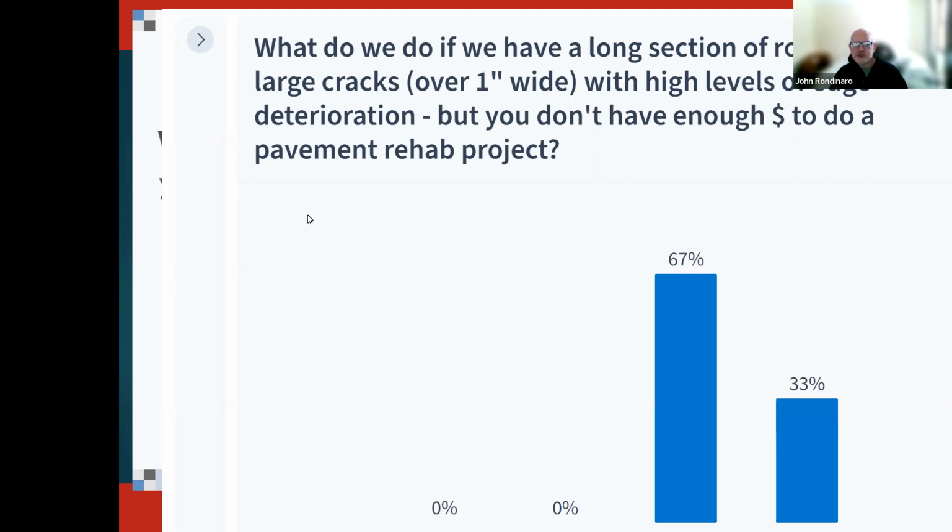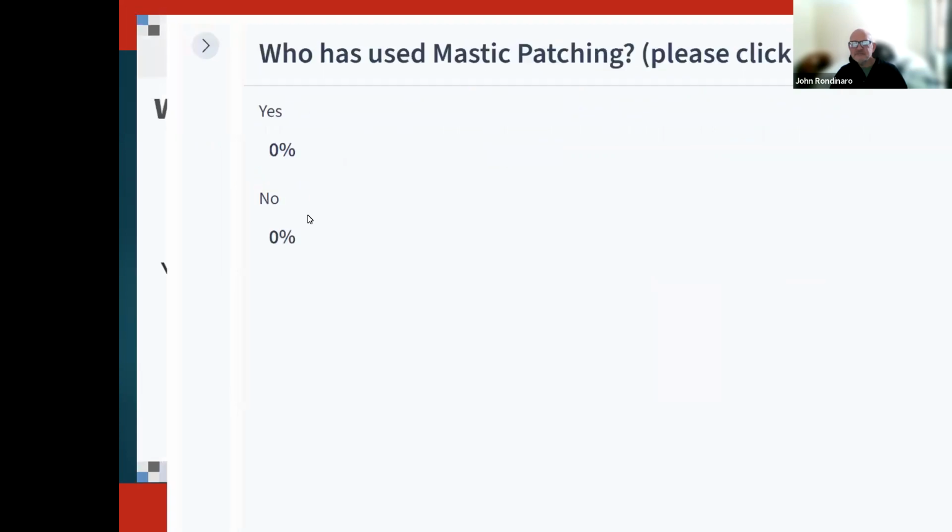Jody, what are our answers showing us? Crack seal? Okay. It looks like a handful of folks are saying other though, and I think they're right. The folks that are saying crack sealing, yeah, it's over 1 inch wide and it's a high level of deterioration, not going to work. So what are you going to do?